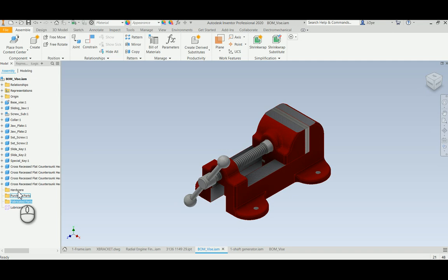And then last on these updates, back to this sheet metal file, this is related to 3D annotations. So for any of you that use 3D annotations, when placing a dimension now on your part or your sheet metal part, you can place your dimension, right click and accept it. The update in 2020.1 is the ability to change what work plane you want a dimension placed on.